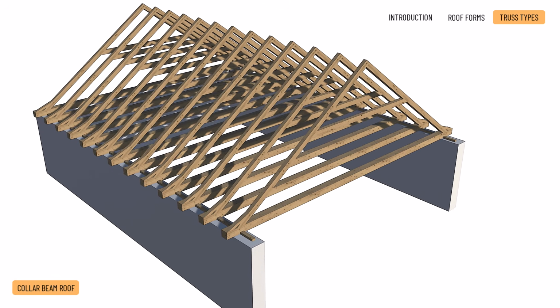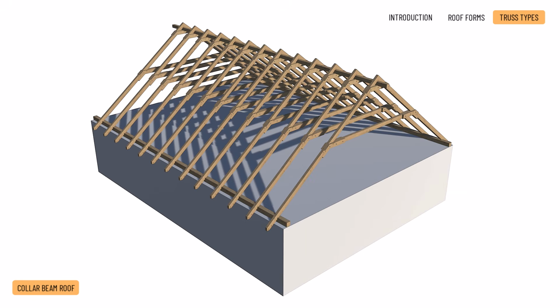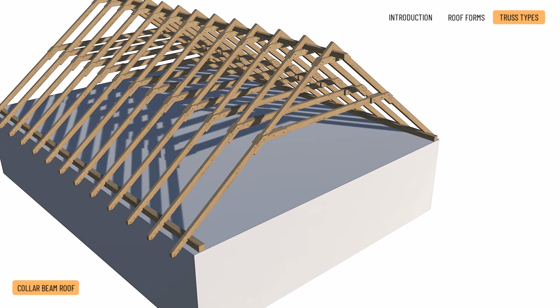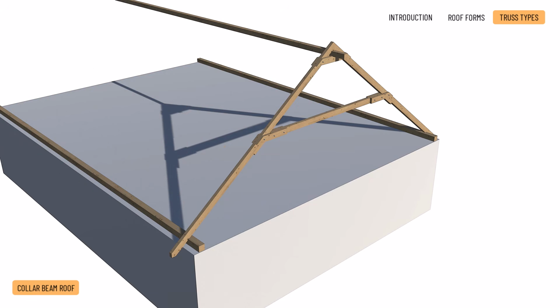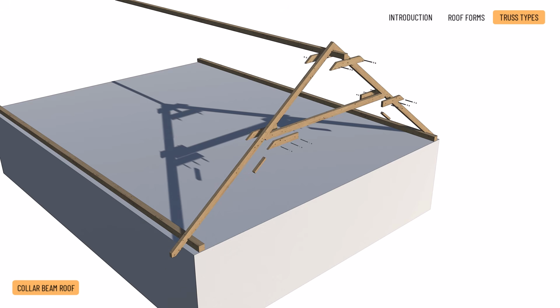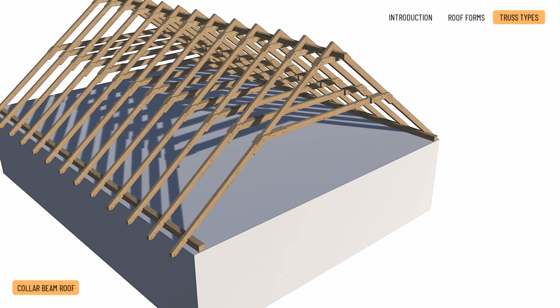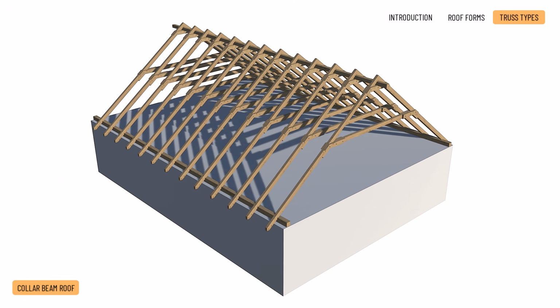In other respects, the roof truss is identical to the closed couple roof. Contemporary construction secures collar beams and rafters with cleats and straps which are fixed in place with stud bolts. All other joinery details remain consistent with standard closed couple roof construction.